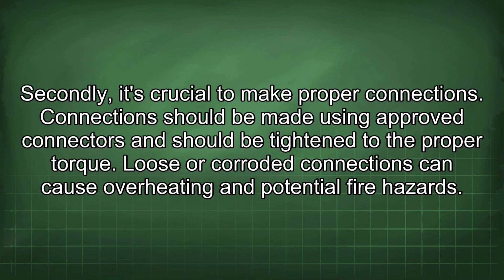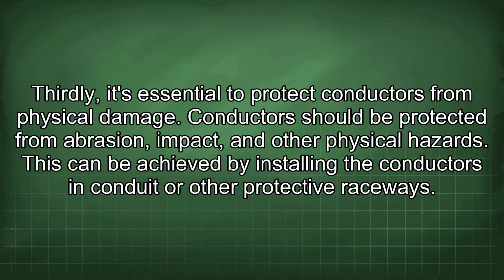Secondly, it's crucial to make proper connections. Connections should be made using approved connectors and should be tightened to the proper torque. Loose or corroded connections can cause overheating and potential fire hazards. Thirdly, it's essential to protect conductors from physical damage. Conductors should be protected from abrasion, impact, and other physical hazards. This can be achieved by installing the conductors in conduit or other protective raceways.